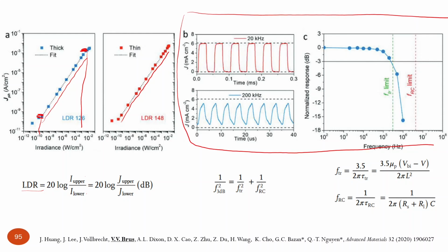First, it's how the photocurrent of the photodiode depends on a fast changing signal. So here we have on, here we have off. So repeatedly we have this turn on and off of a light signal, and you see that at 20 kilohertz, this given photodiode, it's an organic photodiode, which I gave as an example from our recent paper, works quite well. It repeats the square shape of the optical signal, because you clearly can see when it's turned on, it goes to saturation here. So it means that the photodiode responds adequately fast to this signal, and then quickly turns off.